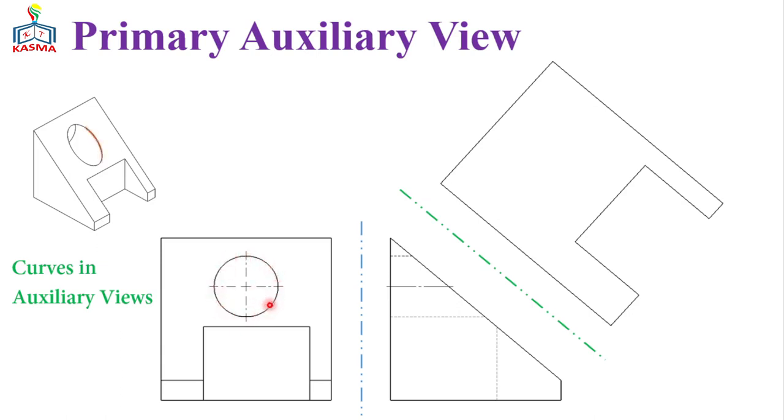If you look here, this is just the circular feature on the front view, and then this one will be on the left side view. So the circular feature is on this portion on the left side view from here to here, which is represented with the hidden line. Now let's divide this circle into a number of sectors. If the number of sectors increases, then the accuracy of the represented view will increase. And if you divide this into fewer, then the representation of the surface on the auxiliary part will not be as exact as expected.